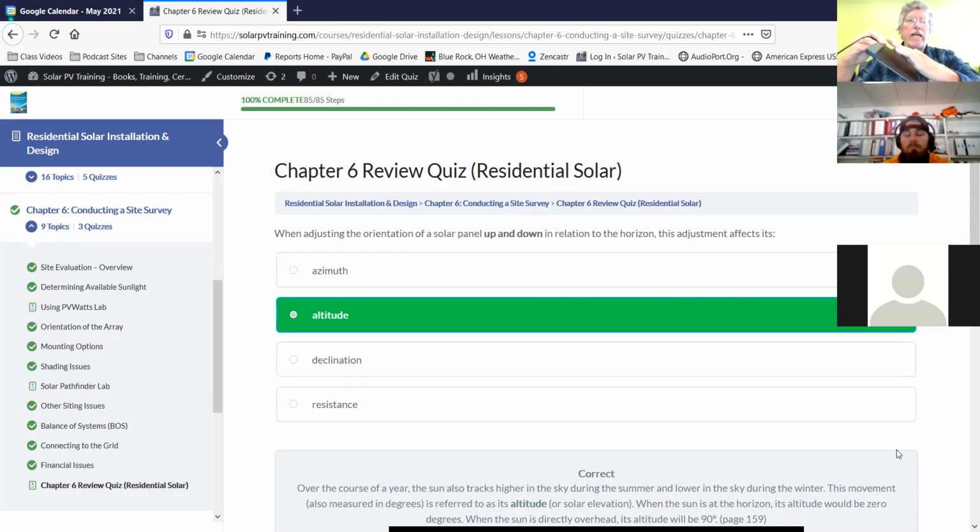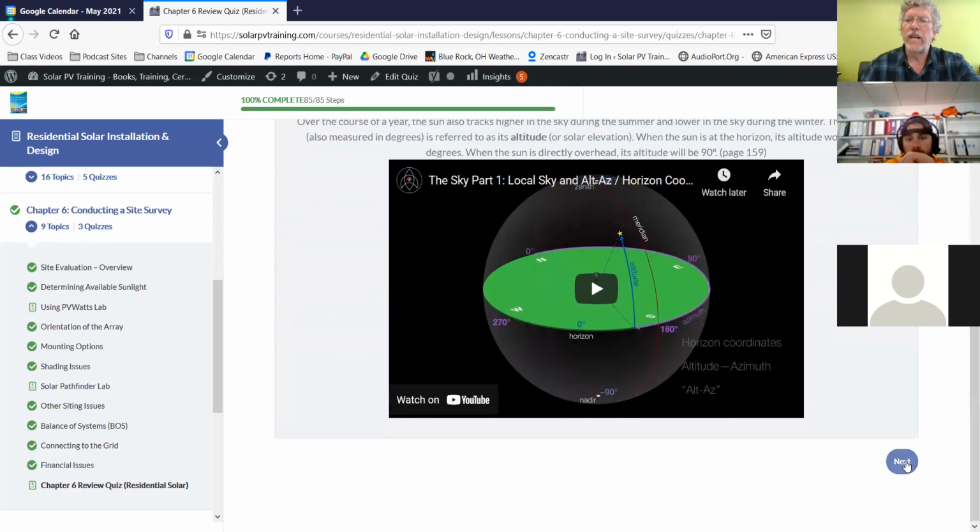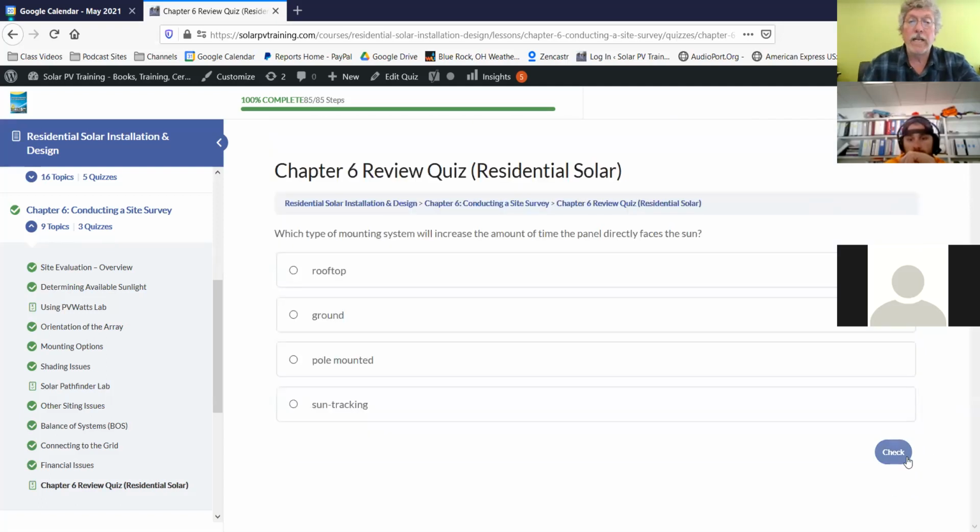One is aesthetic. If you do this, it's going to look terrible, but it also puts stress on the panels and can pull them off of there. So most of your pitched roofs are going to have a flush to roof system. If the pitch of the roof is 15 degrees, then that's going to be the pitch of your system. And if the orientation is not true south, then your orientation is not going to be true south. You'll just have to work around that.